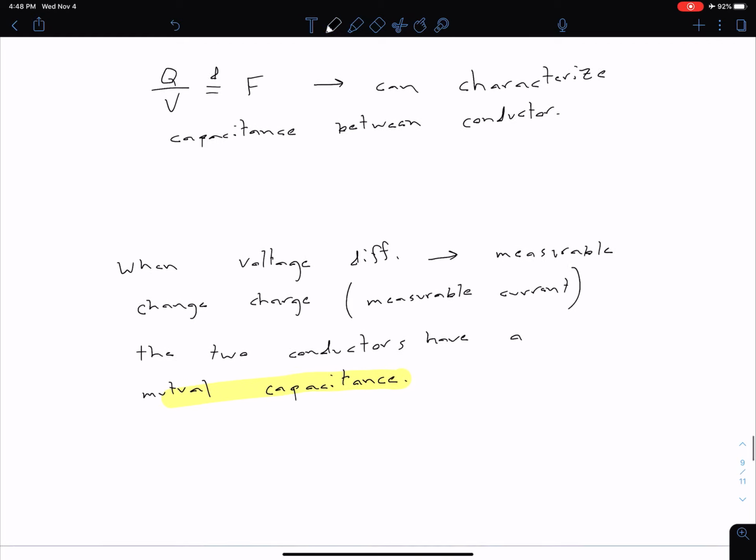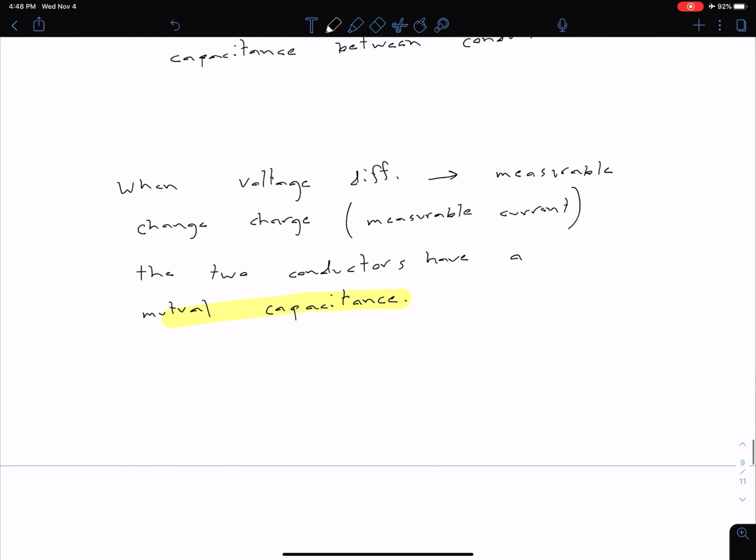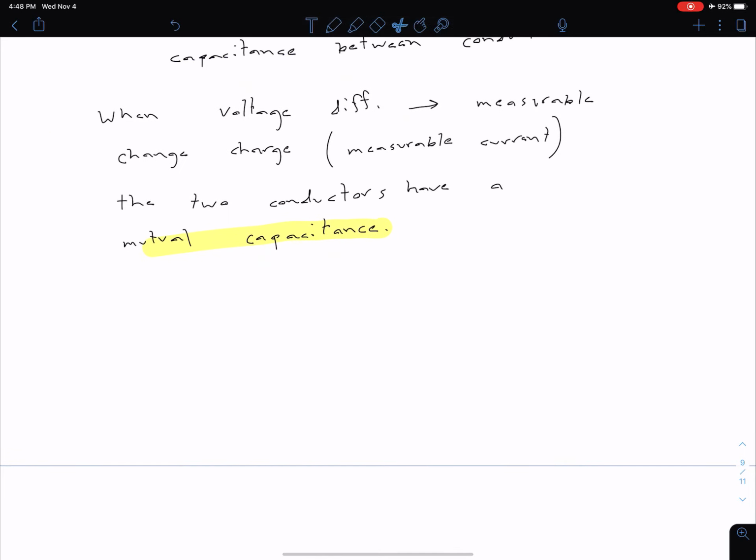Okay, and so typically our capacitive EMI, so let me move this up a little bit because we're running into our circuit on the next page, is going to be more common in high impedance circuits. So capacitive EMI is more common in high impedance circuits.